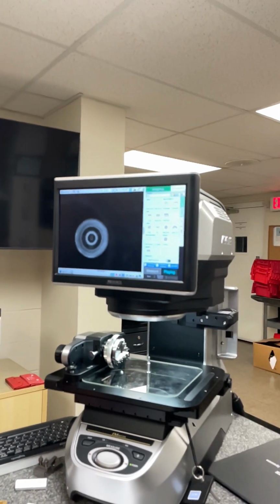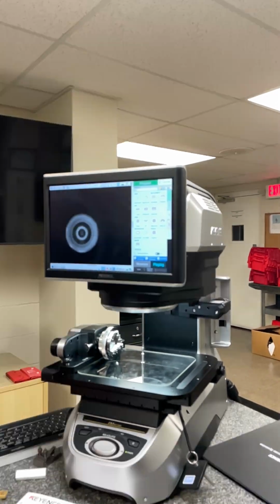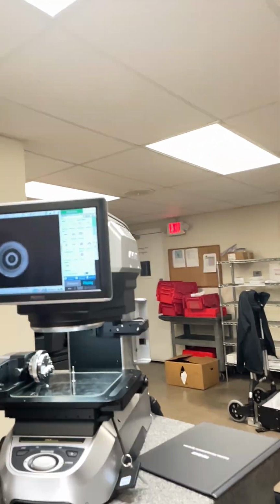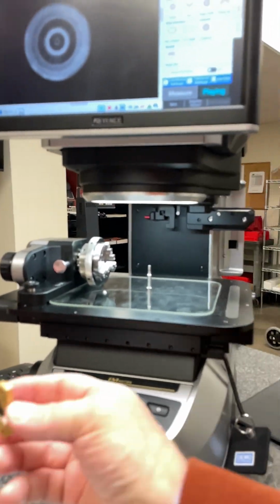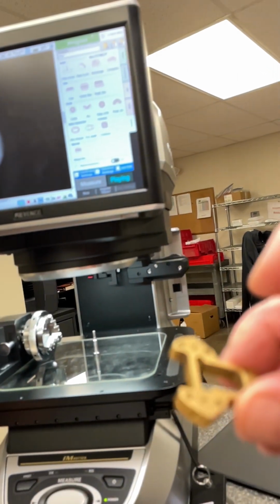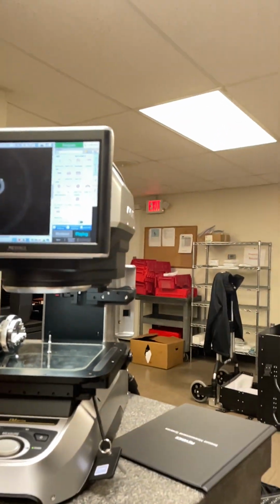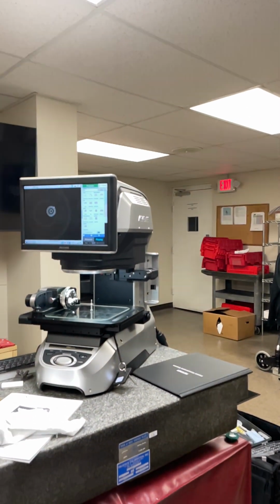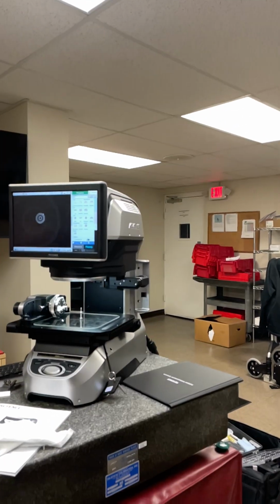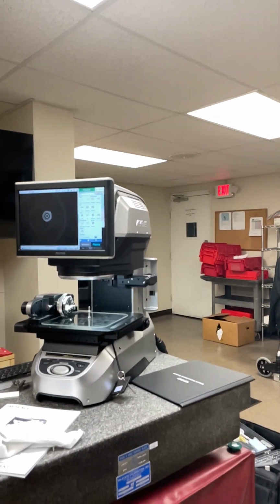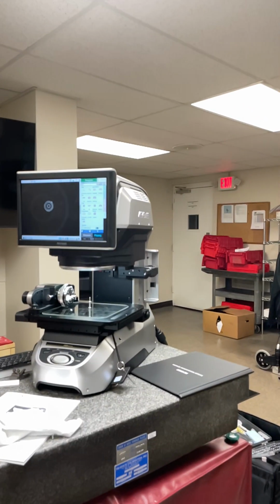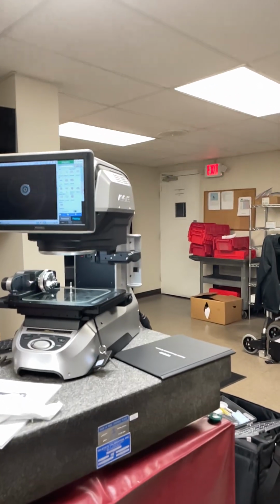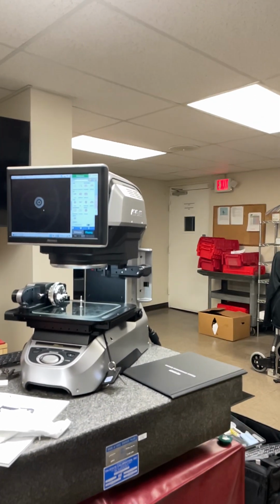Right. You could go in with the height gauge as long as that hole is larger than 1 millimeter. We could go in, touch off, and then touch the glass. But the only other way you could do that is non-contact, which is a different thing that we sell, kind of like a tool maker's microscope version of this. We could do non-contact height measurements. The only way I could do it that way is with that, unless you guys had a correlating feature on the outside to go in on there. That's the only way I could see it working.